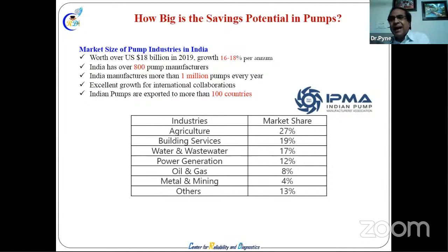So then the next project I will obsolete the VFD. I will take a right size pump, right size driver for the particular pump. So people should learn from the mistakes they are making. VFD is not the only solution. VFD also brings disadvantages.